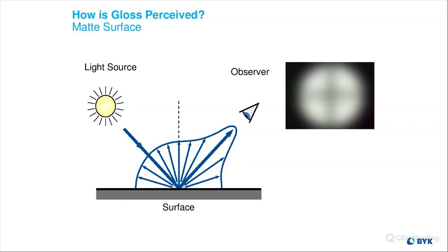So if you're not able to measure a true value of the gloss due to something transparent or surface texture, is that where you do your comparative measurements, multiple times, then take the average, or how do you account for that? Exactly. So if you want to take comparative measurements, you want to take as many measurements as possible. Even if your standard is not ideal, it's your standard, and you want to compare that to the rest of your samples. So you want to take as many measurements as possible when dealing with these situations. Perfect.